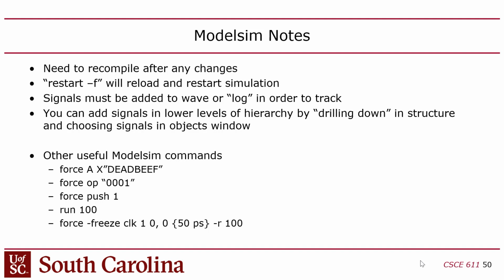Why? Because the FPGA compiler has a timing spec. Remember I told you about the timing spec, it'll tell you whether it's going to meet the minimum timing requirements. So there's no reason to ever simulate with delays in ModelSim if the synthesizer is going to guarantee you that it's going to meet your timing spec, right? So I don't know why they have that timing capability in ModelSim. It's useless, right? Because the CAD tools have timing closure built in. The only thing you're using ModelSim for is the behavior to test the functionality, not to test the performance in terms of the logic delay, okay?